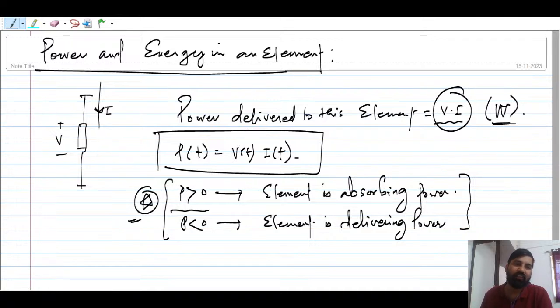And if a voltage source is there and the current is flowing from minus to plus, the power is going to get delivered. So you always have to see the direction in which the current is flowing, I mean, through which terminal the current is entering. I will discuss this with respect to passive elements and all, right? So I think this is clear.